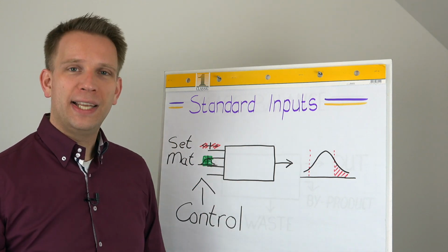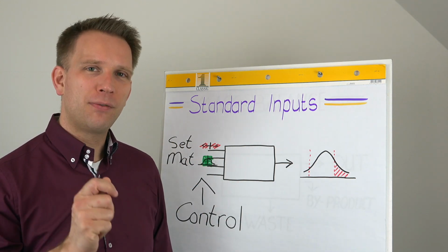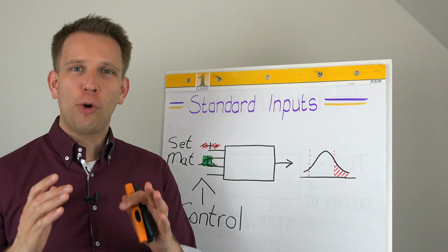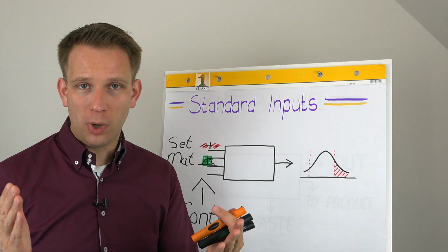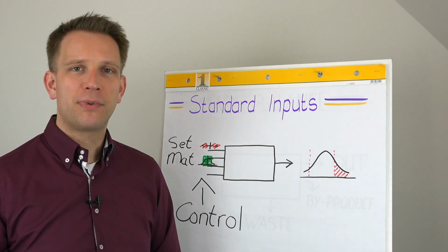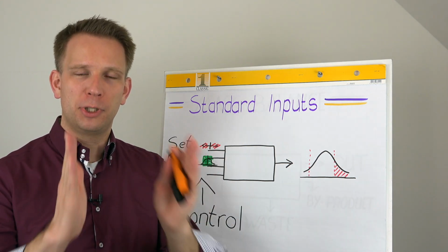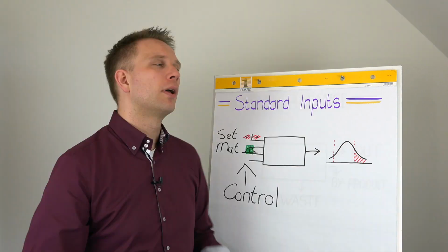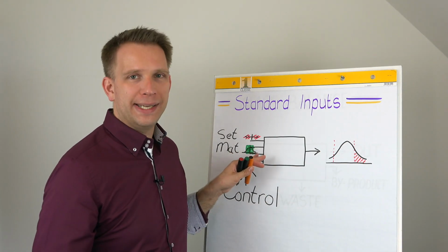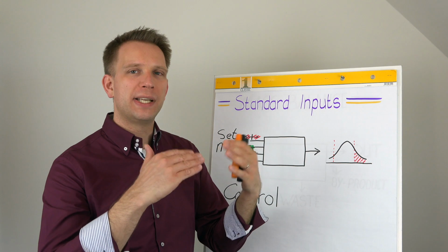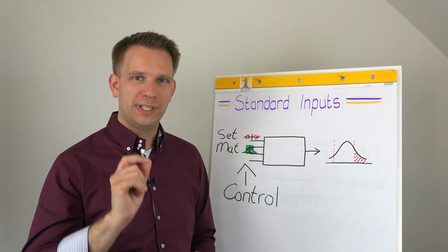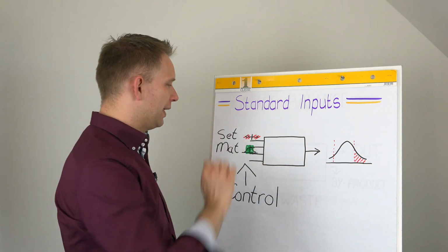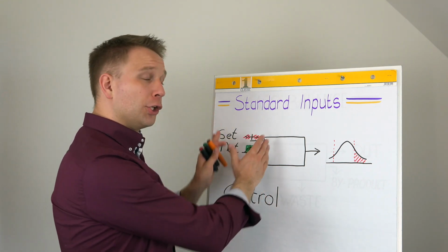Go through standard operating procedures, and every time that you see that an operator is allowed to set some parameter between X and Y, that is something you would like to improve to become just one value. Again, when you see that an incoming material has to be between this and that, that's okay. But set points, so choices that we make, only one. And then you check for that.